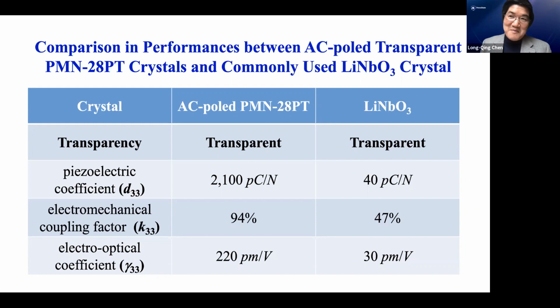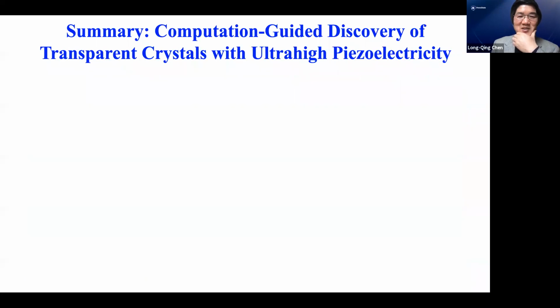Or if we can make it like a screen, because of piezoelectricity, if you can push it, you can generate electrical energy. So in principle, you can use it like a touch screen. Of course, using a single crystal to do this is expensive, but we are thinking about maybe also doing a composite, lining up the crystals, and you do AC poling, you may be able to make it transparent also.